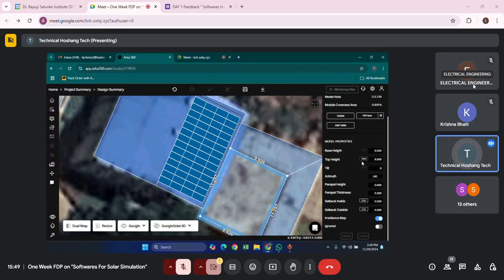Why I am saying 20 panels is that each 335 watt panel has a normal operational voltage of up to 38 volts. So when we multiply 38 into 20, you get an optimal voltage of 760 volts, which is the minimum working voltage for the solar inverter, right?